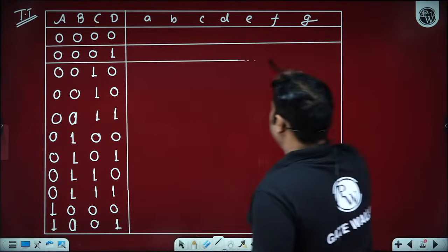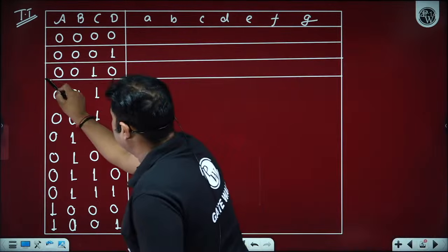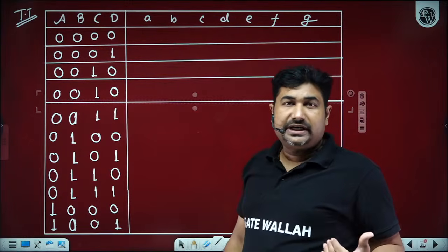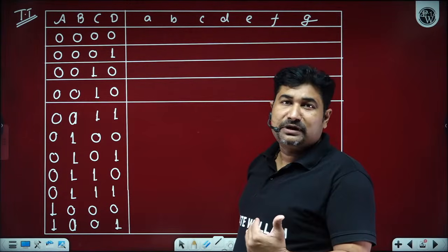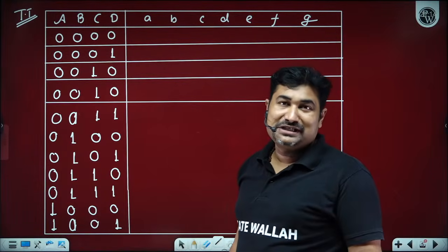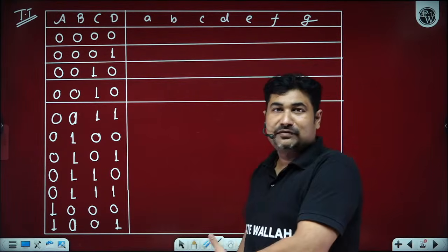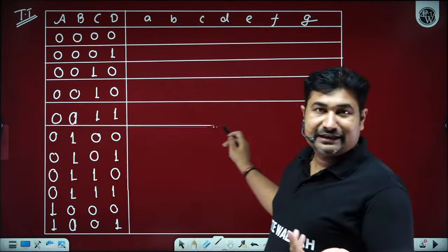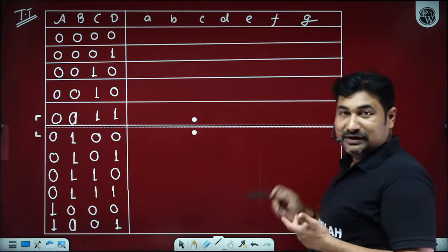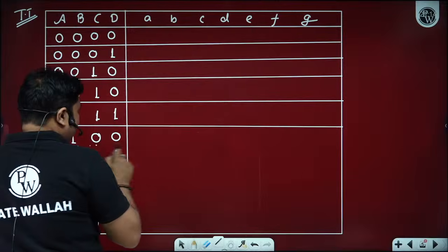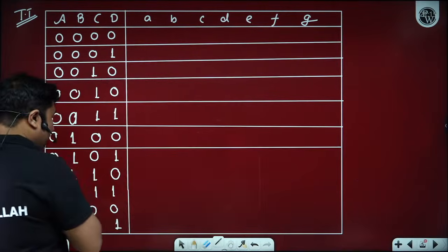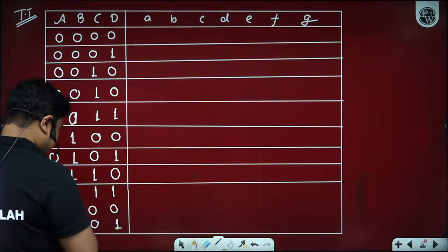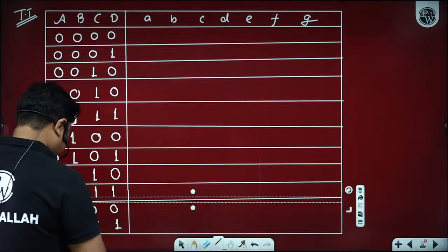Now, can you please tell me what are the particular combinations? Hoping all of you are now able to understand which topics we have completed. Till date, you will now be able to understand how to design any desired combinational circuit. So this is a practical example of designing a desired combinational circuit. First of all, identify the input, output, and their relationship. Next, construct the truth table accordingly, and then write logical expressions of the outputs and implement the logic circuit. How many of you are now able to understand, beta ji? Great. So now please observe here.